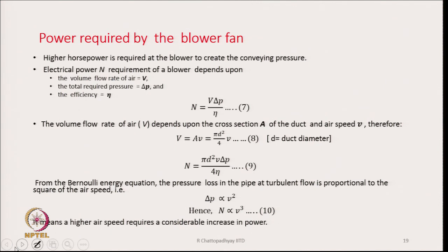The other thing is power required by the blower fan. How much power is required? We are very much concerned about the energy always, how much energy is consumed by the machines. We always need energy efficient machines. So, we also see there are so many blower fans which are working in the blow room line, and therefore, we have to also see how the energy is connected to the operational parameters. So, higher horsepower is required of the blower to create conveying pressure.